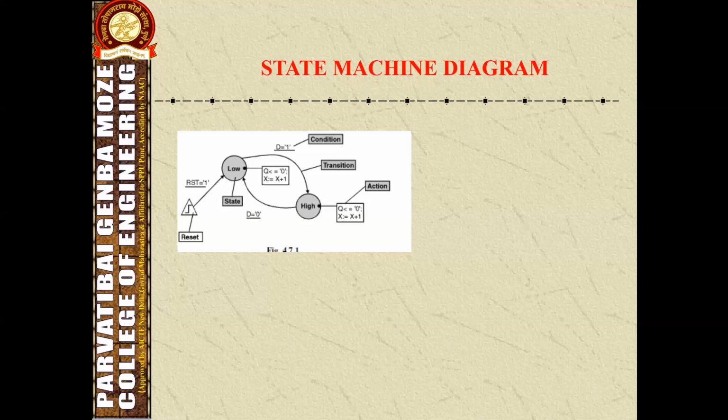So next, the reset. The machine transitions to the state defined as the machine's reset state if the reset condition is true. The transition to the reset state is asynchronous or synchronous. The machine with the asynchronous reset transitions to the reset state when the reset condition becomes true.